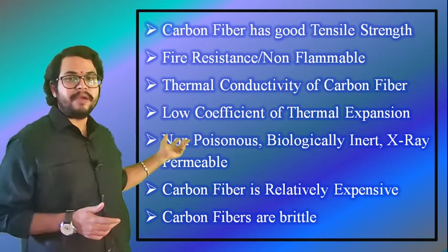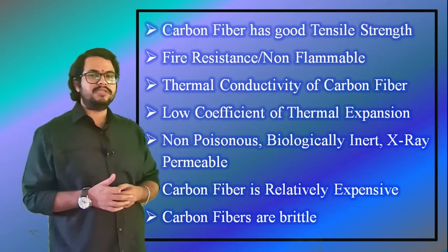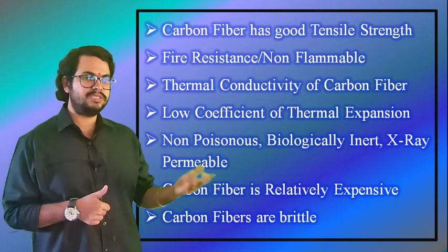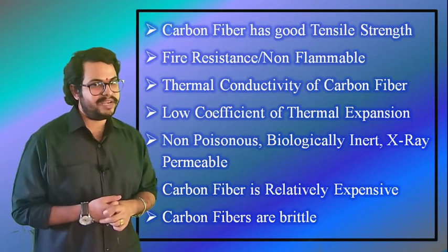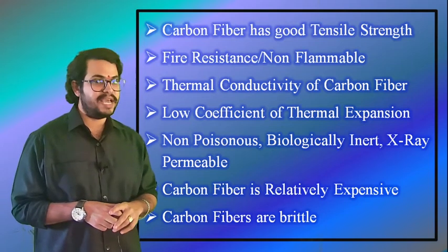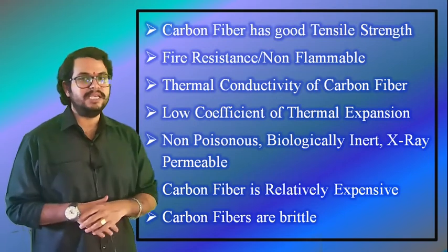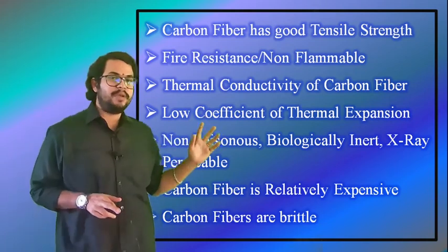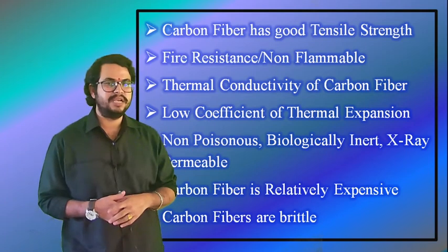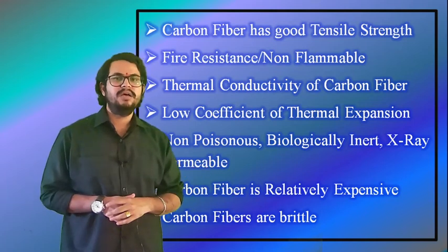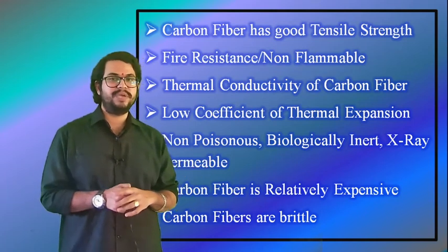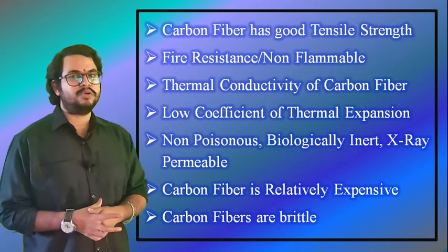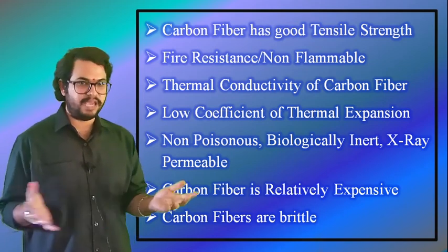Carbon fiber is relatively expensive. Although it offers exceptional advantages of strength, rigidity, and weight reduction, cost is a deterrent. Unless the weight advantage is exceptionally important, such as in aeronautic applications or racing, it often is not worth the extra cost. Right? The low maintenance requirement of carbon fiber is a further advantage. It is difficult to quantify cool and fashionable, but carbon fiber has an aura and reputation which makes consumers willing to pay more for the gadget of having it. You might need less of it compared to fiberglass, and this might be a saving.